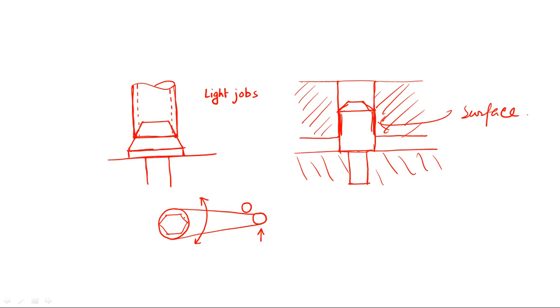The next point is, suppose this one is your product, and in this product you have provided support at this end and at this end, and the load is acting. Now if this gap is too large, then this plate can be deflected due to the application of the force.